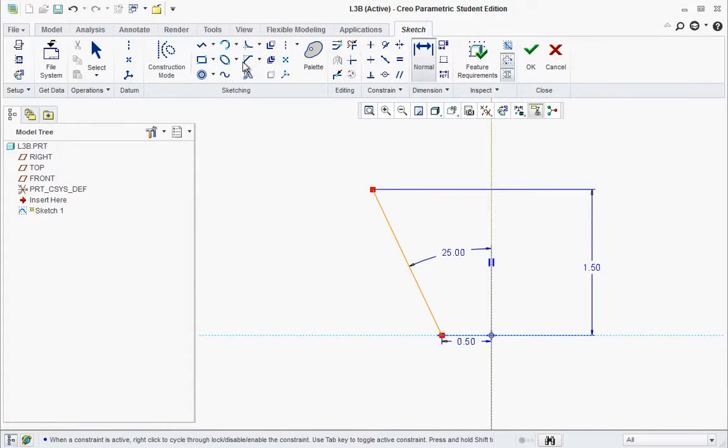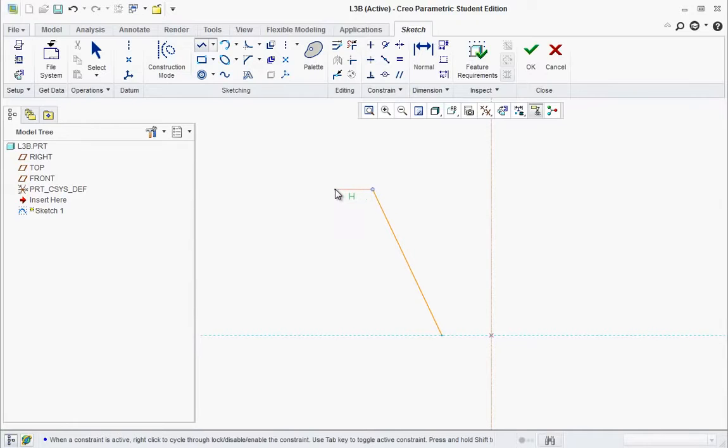And from here we could continue on drawing the rest of the geometry. So this gets dragged out a little bit horizontally, drag it down, and try and find the automatic parallel relationship. Otherwise, if you can't get it, you could force it with clicking on parallel there, but you don't need to do that right now. You'll see it will snap to parallel. Click and drag this out horizontally, find parallel once again, drag this in, click and drag down, find parallel, and connect.